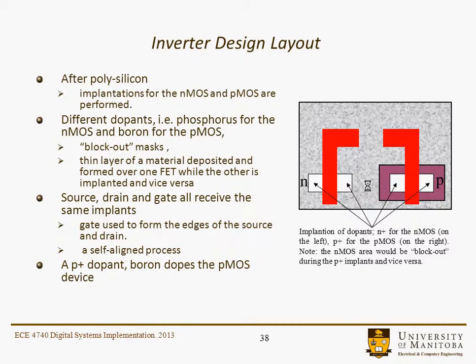Sort of after the polysilicon, then you make the transistors N and P type. So this is a heavily implanted N type region. This is protected during that point in time, and when this is being implanted P type, this whole area is protected, and this area here goes through an ion implantation stage where the material becomes p-type.